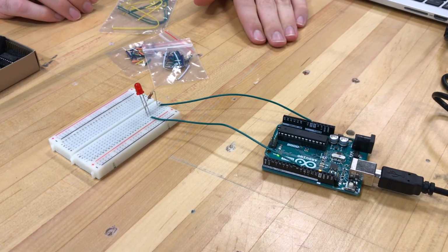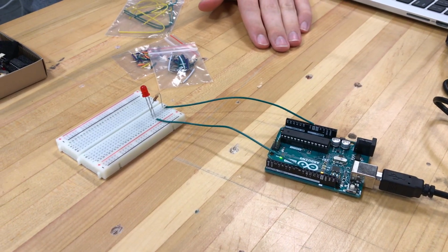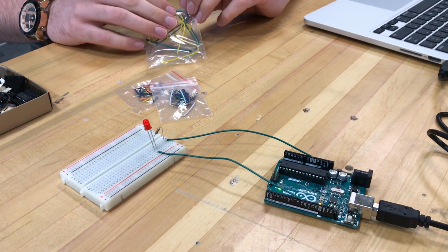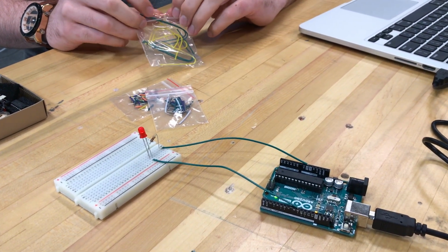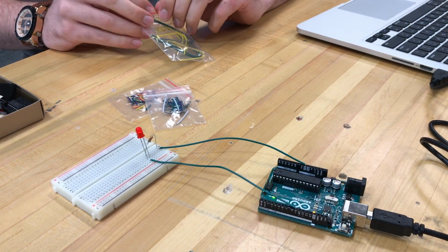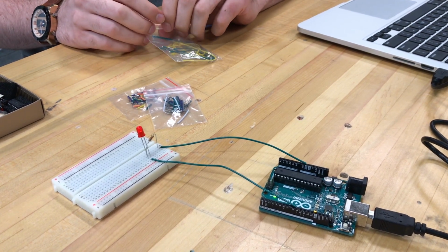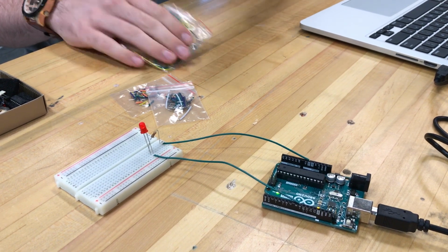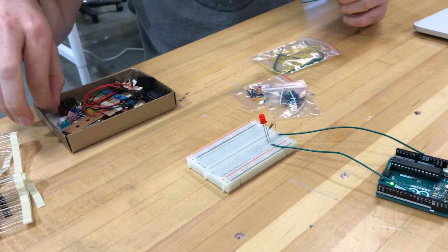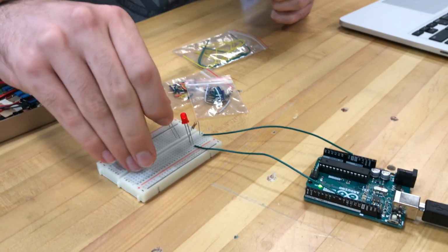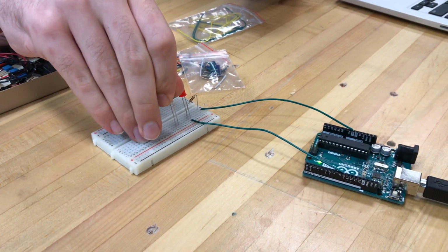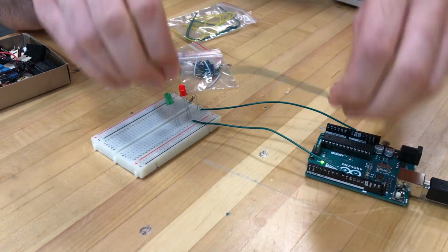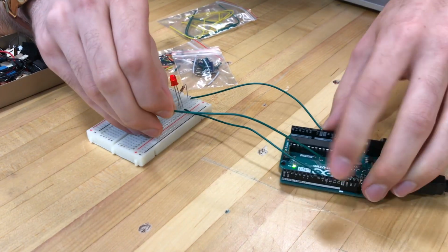For your sign project, you'll need at least 2 LEDs, so we're going to go ahead and add a second LED circuit. Once again, we have to connect the LED in series with a resistor between a digital pin and ground. This time I'm going to pick digital pin 8. So let's start out with an LED, place it on the board. Once again, the long end of the LED is positive, so we'll connect that one to our digital pin.